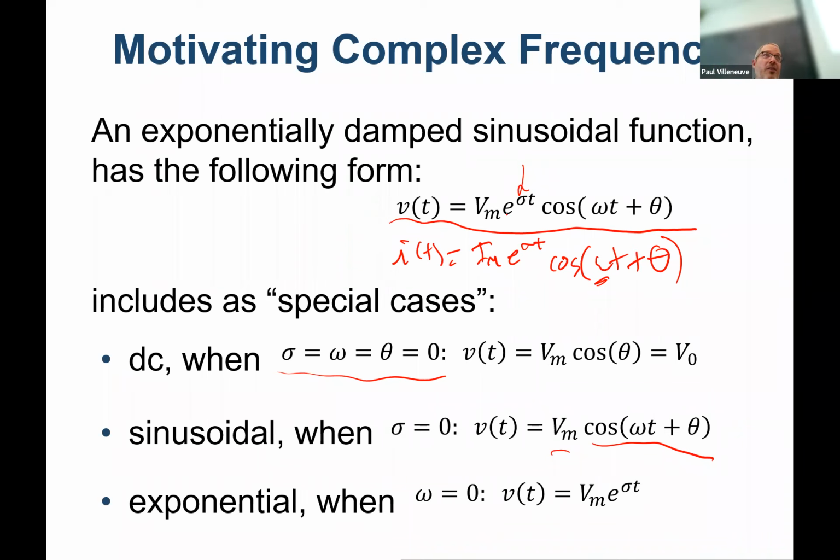So you'll see that this gamma term is inversely proportional to our time constant. This is just a standard sine wave or cosine wave with no exponential term. Most of the time in sinusoidal waveforms, you don't want DC. In our real world power system, DC would cause major problems. It's very rare that you want DC and AC combined, except sometimes in amplifiers, where you set the center point, like a class AB amplifier. You set the center point in the middle and it can go up or down on the sine wave to go where you need.